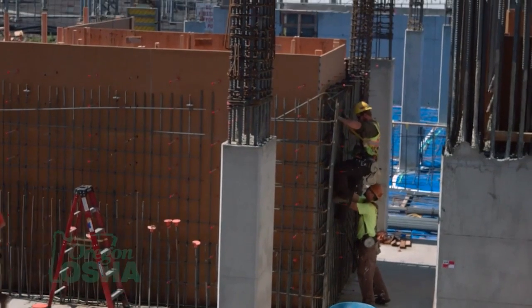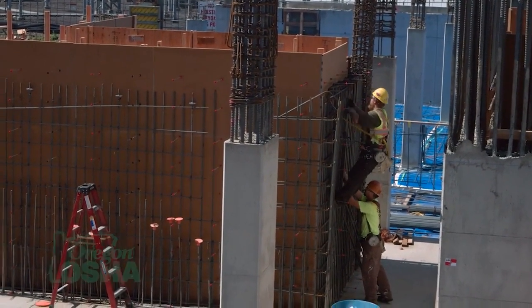When I need to work on a ladder, rebar cage, column, any place where I'm climbing, and I need to take both my hands off to get the job done, I no longer have 3 points of contact. So a positioning device is something I can connect that allows me to connect to my structure and maintain that third point of contact. I can lean back into that positioning device, work hands-free, and still maintain 3 points of contact. With a work positioning device, I also have to make sure that it is short enough that I'm limiting my free fall to 2 feet or less and still have a 3,000-pound or 2-to-1 safety factor on my anchor points.